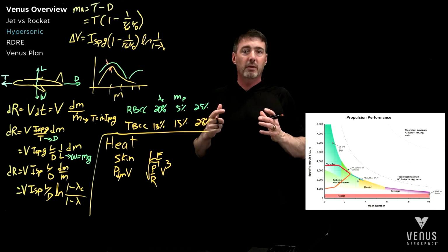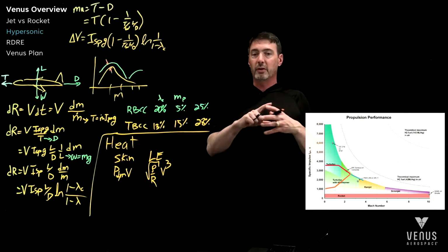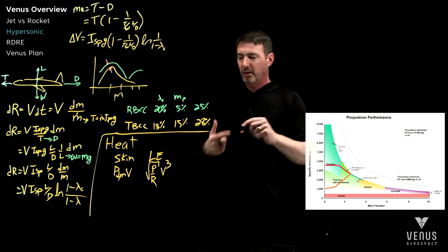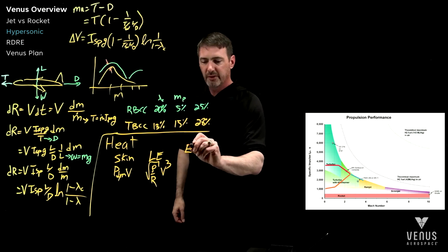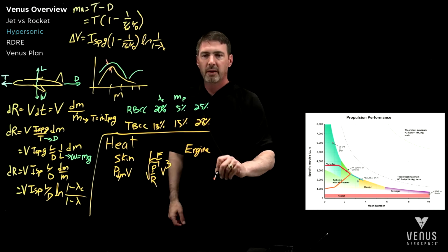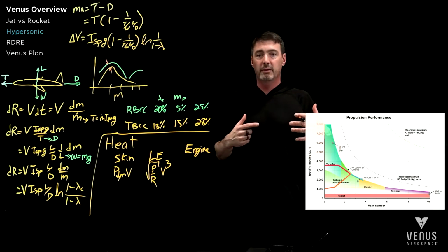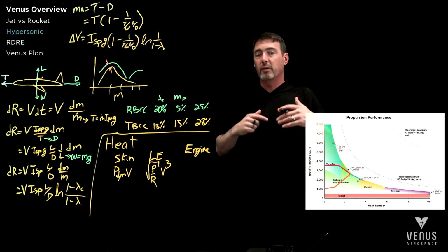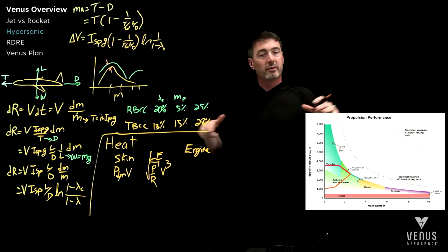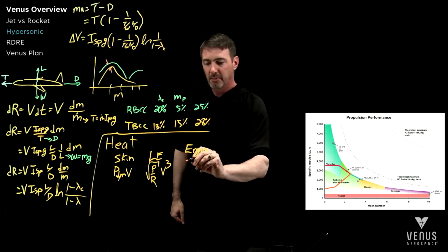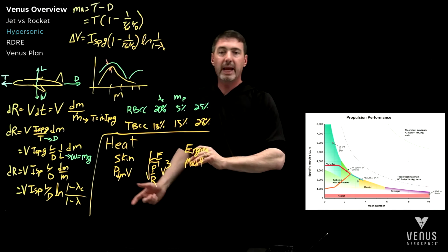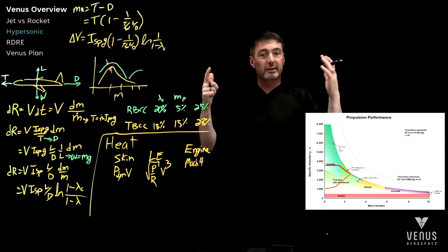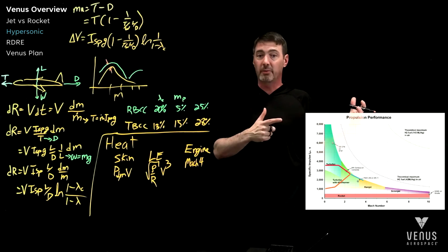And then finally, for anybody using a ramjet system, right? If you're drawing air in, whether you're turbine-based combined cycle or rocket-based combined cycle, we all are transitioning to a ramjet. You have to think about the heat problem inside the engine itself, because that air on the inside, whatever that hot air is and the hot components that are touching that air, they are internal. They're not able to radiate away to the environment. And so just to give some idea of what those temperatures can be, at Mach 4, when you are compressing air, you're slowing air from Mach 4, and through some shocks, you get some compression, which is right back to the suck squeeze bang blow, an important step in the ramjet operation.